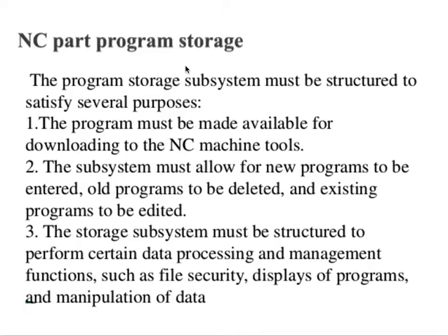The DNC program storage system consists of active storage and secondary storage. The active storage is to store NC programs which are frequently used, and it can be readily accessed by the DNC computer to drive an NC machine in production. A typical mass storage device for this purpose would be a disk. The secondary storage would be used for NC programs which are not frequently used. Examples of secondary storage include magnetic tape, tape cassettes, floppy disks and disk packs, etc.